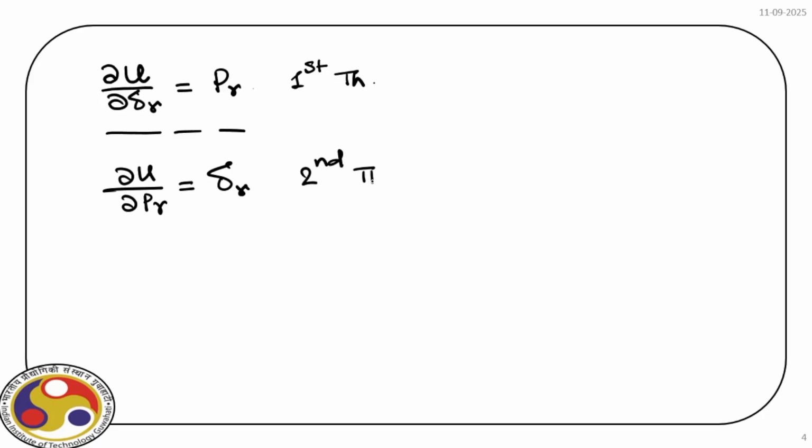And we have also solved some examples using this theorem, and you have seen how we can quantify the actual strain energy: bending strain energy, shear strain energy, and torsional strain energy, right? For every elastic deformation, we can quantify the strain energy, and the moment we quantify the strain energy, we can find out the displacement along the rth force, and that gives us the clue how to evaluate the displacement.